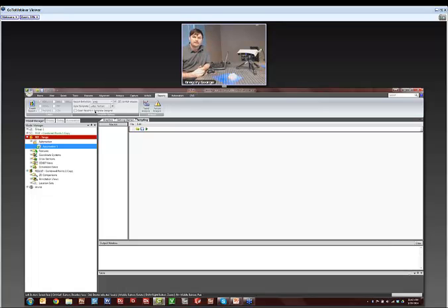Now, it does pretty good with the different surface finishes, but it'll have the same limitations as GOM does with blue light and white light technology. We overcome some of those with processing like the HDR mode that I highlighted before, but there are certain colors or extremely shiny objects that it's going to have issues with. That's just the nature of the physics problem that we're overcoming with the type of technology we're using, and it's going to be inherent in both devices.